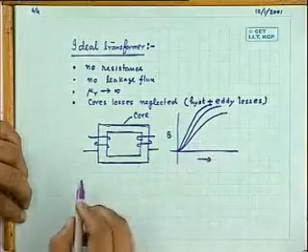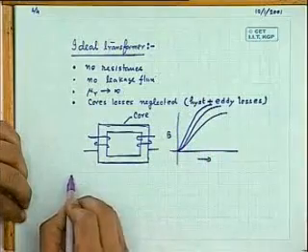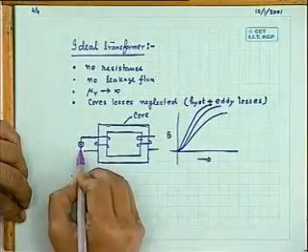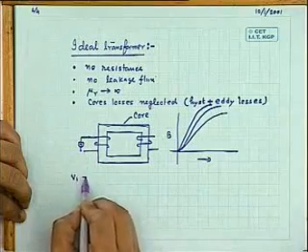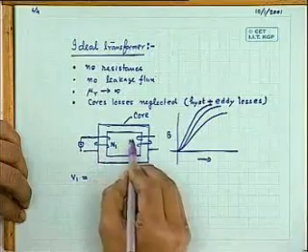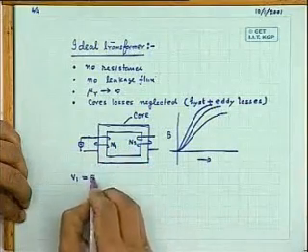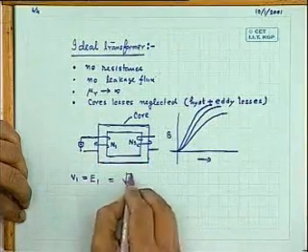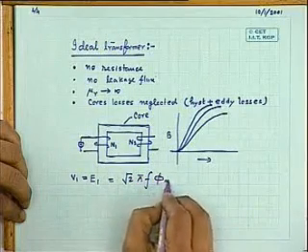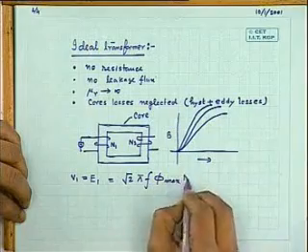And the second thing we did also, that the applied voltage, the magnitude of which will be the same as the induced voltage in the primary winding as well as in the secondary winding, is given by root 2 pi f phi max into N1.